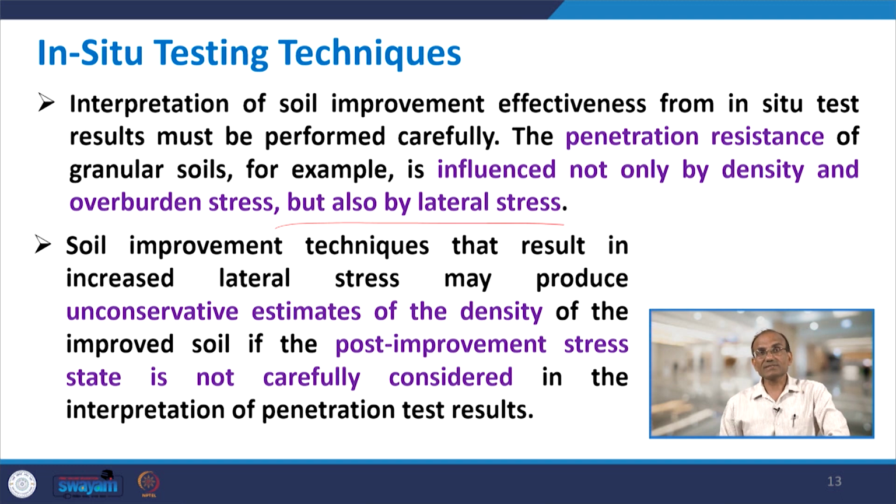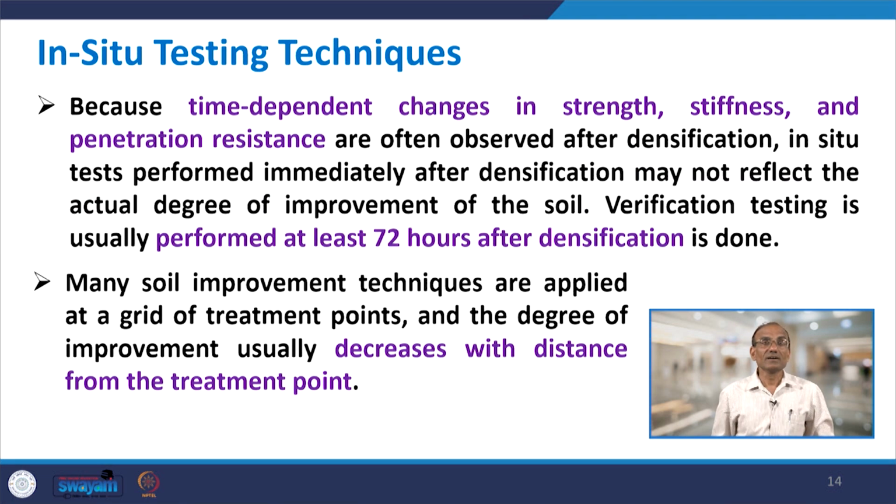Soil improvement techniques that result in increased lateral stress may produce unconservative estimates of the density of the improved soil if the post improvement stress state is not carefully considered in the interpretation of penetration test results. So, we need to consider the stress conditions also while interpreting these results. Because time dependent changes in strength, stiffness and penetration resistance are often observed after densification. That means with time, today you may have one condition in the field, after a few days it could be a different condition.